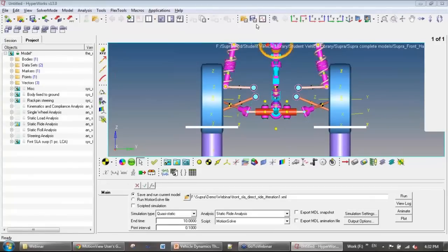Similarly, you can load whatever reports you want, like you've been doing for the hypergraph. Similarly, you can do different analysis. If you want to analyze the steering and how the camber changes with steering, which is your bump steer characteristics, you can look from here.